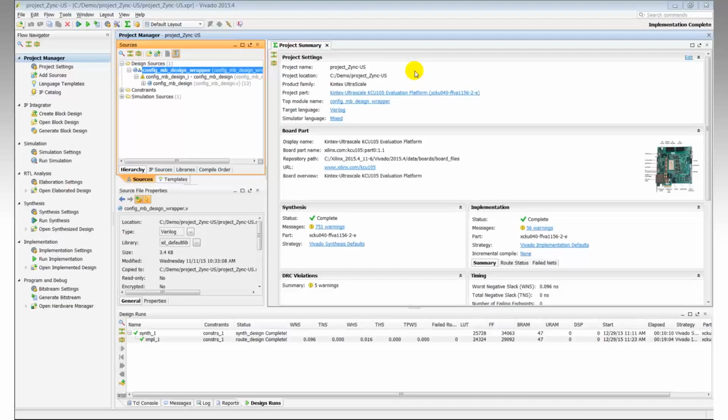All of the tools and tool features associated with the Vivado Design Suite are integrated directly into the IDE. Its primary purpose is to facilitate the Vivado project flow. However, it can be used at certain points during the non-project flow for design analysis, constraint assignment, IP configuration, pin planning, etc. In this example, I've opened up one of our configurable example designs targeting a Kintex UltraScale device with an embedded MicroBlaze design on one of the Xilinx evaluation platform boards.